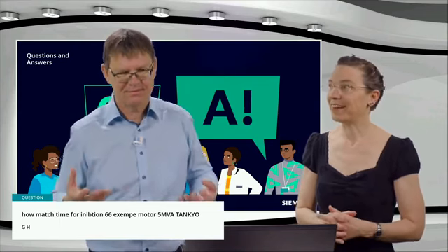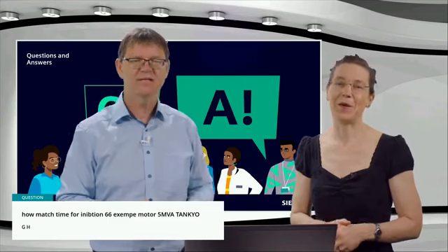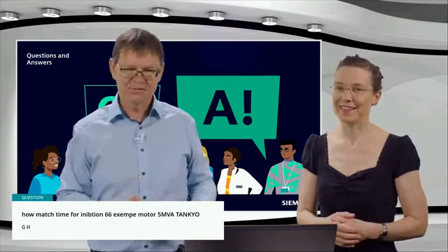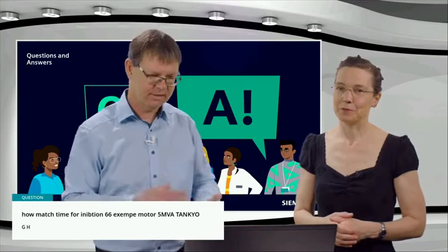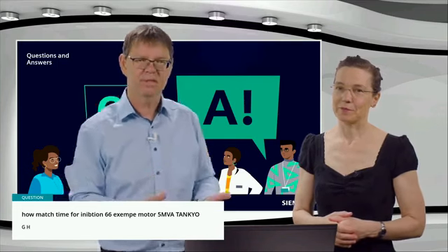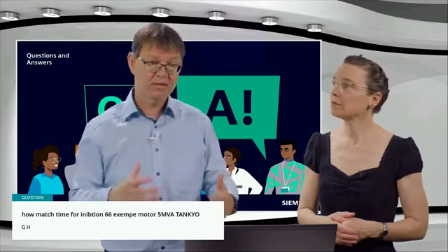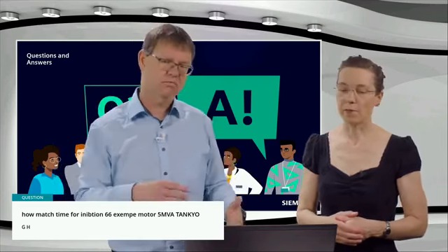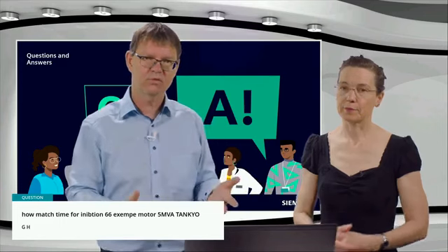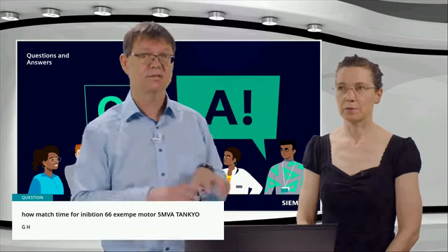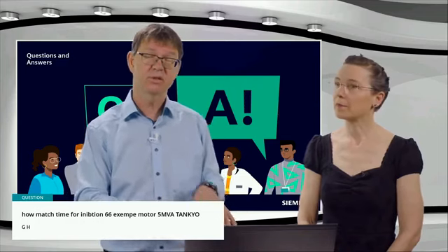Okay. Difficult, because this depends on the motor data. I cannot give you a recommendation how to set this function if I don't have the motor data. I tried to show you with one example how to make this setting. Basically, you need a statement of so and so many starts from cold and warm state of the motor, and then the starting time and starting current to which these statements belong.